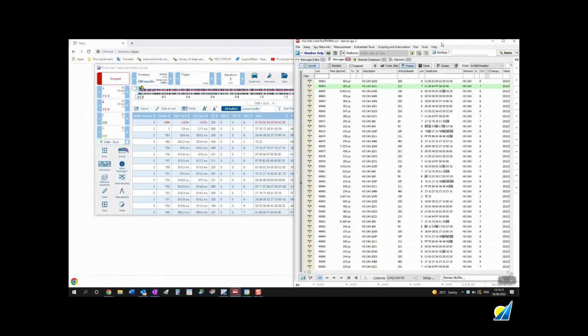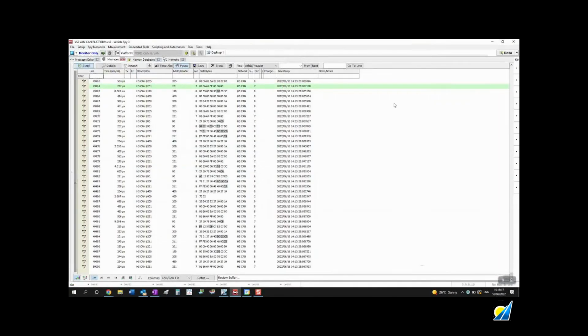Okay, so coming back now to Vehicle Spy, what did that detect? No bus errors. And we can scroll back through here, the last 50,000 messages, and we're all good. No error counts. So I think we can conclude that that is a fix. Thank you again, team at AC-Tronics.